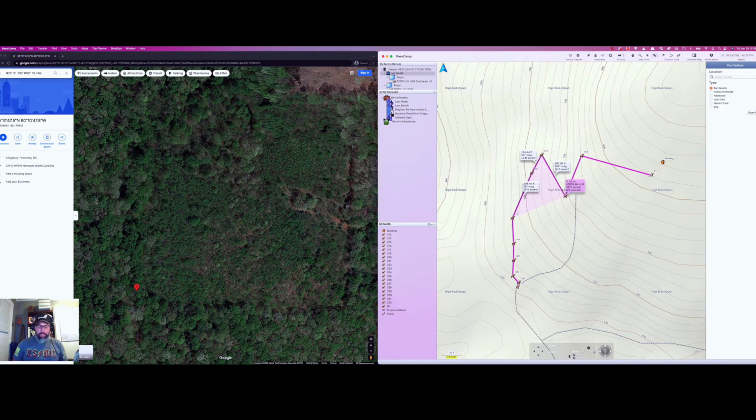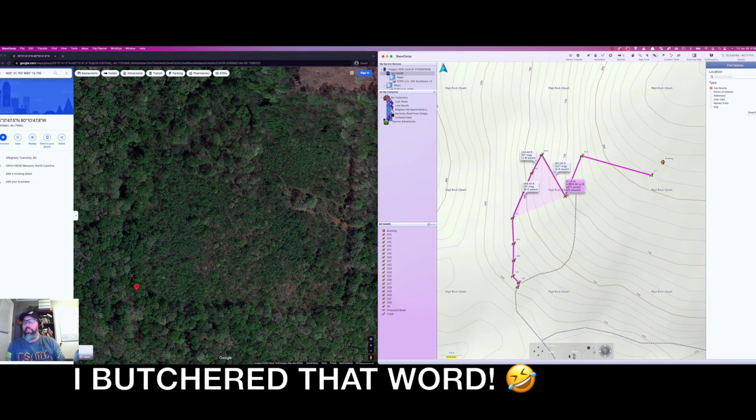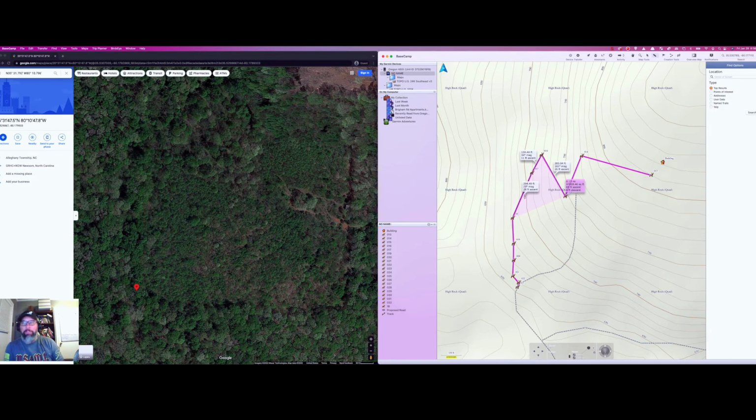So we said 65 feet elevation gain divided by 685 feet, we'll just say, round it up. We're looking at a 9.4% slope. If you round that up, it's 9.48, so you say 9.5% slope. So we're still below 10% slope, which makes it a lot more navigable. It's easier to drive and so forth on a driveway.